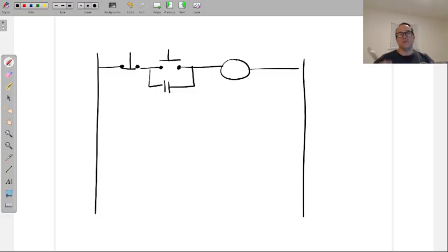So here's your options when you're building a control circuit. First of all, you have to try to figure out what it is that's going to go into this circuit. So if it's something very simple, like one motor with one push button start stop, then there is no need for a control relay right now. We can make this load here the motor starter, and yes, we'd have an overload there. I didn't want to add too much.